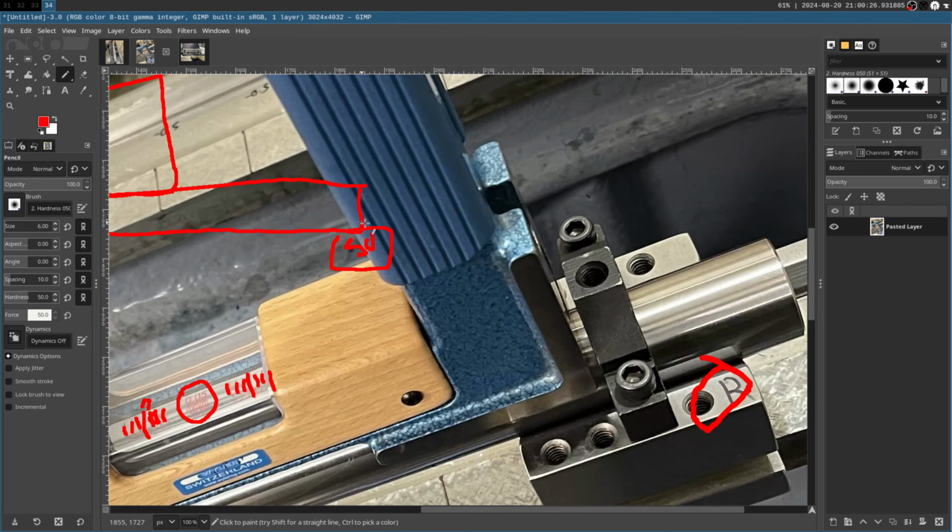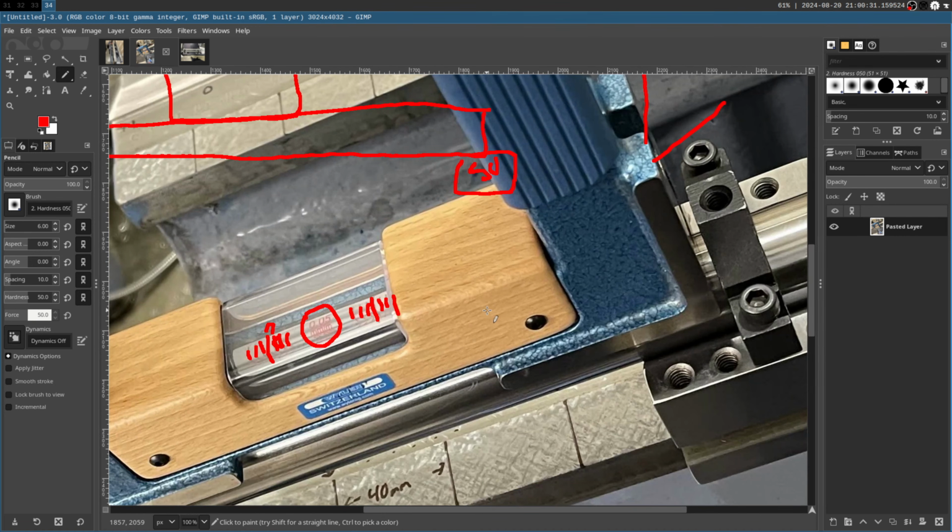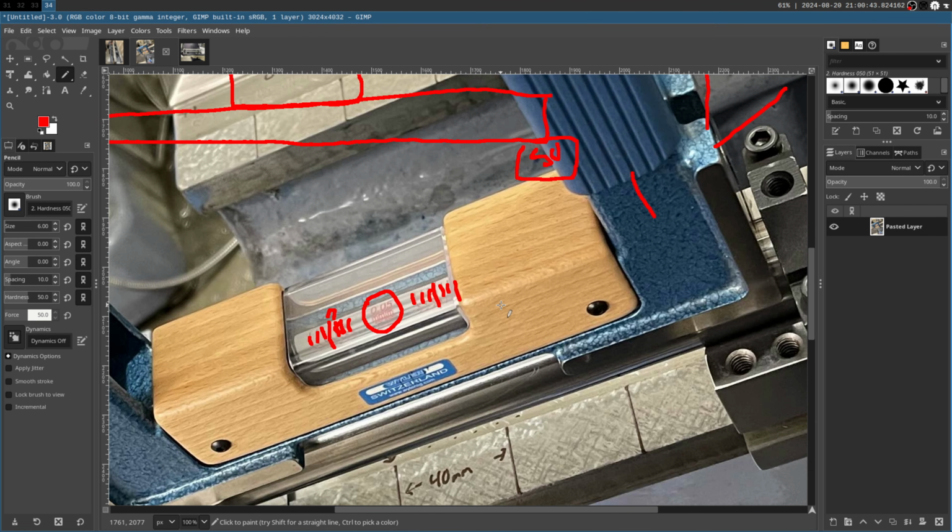So this level here has 2 little set screws in there to adjust, basically little set screws that push on the vial and will adjust the twist in the vial as well as the elevation of the vial. So right before I do any of these measurements, I'm calibrating that level against my surface plate.